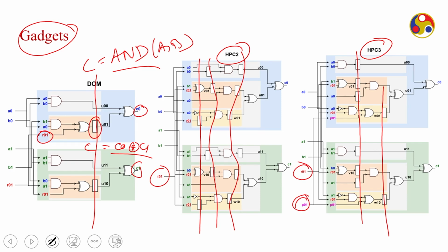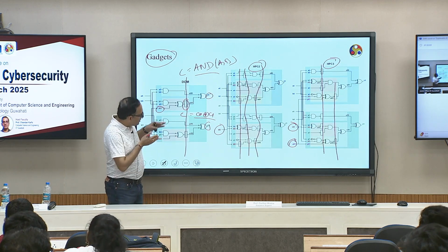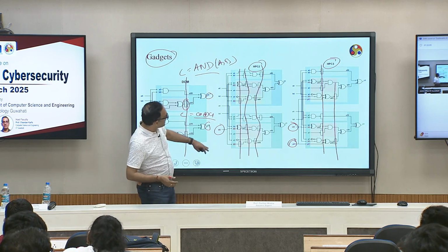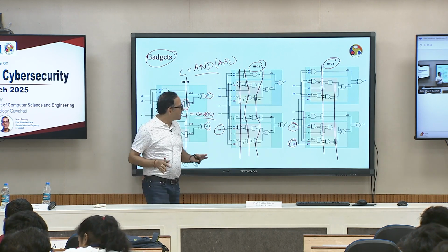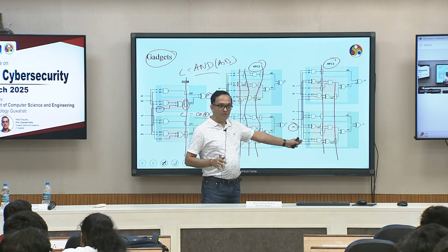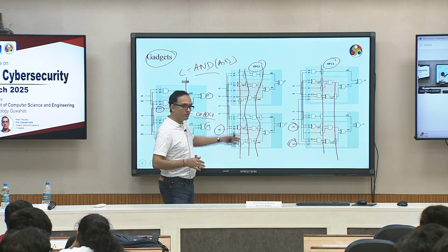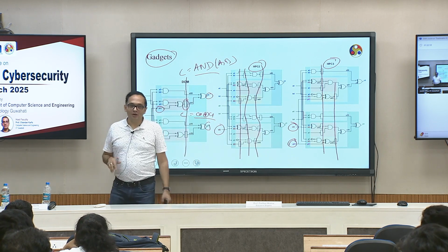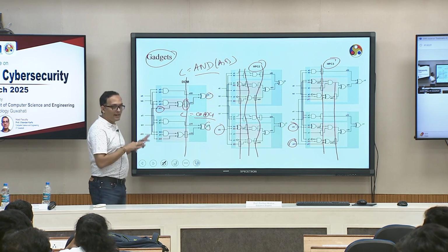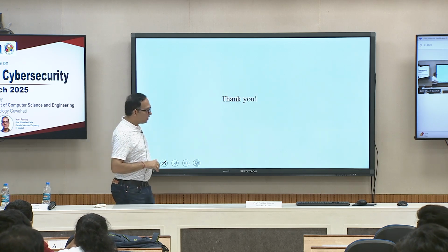So, this is another direction. If you use more randoms, random generation also is costly, right. How do you generate a pure random number? So, some people want to use the minimum randomness, but whenever you use less randomness, your number of registers and latency will increase. So, it is a trade off between the number of randoms you want to use versus the latency you want in your design. Okay. That is a cryptographic designer's job, not our job, but the core idea is this. Okay. That is all for now.